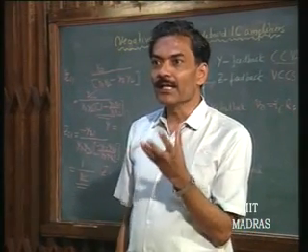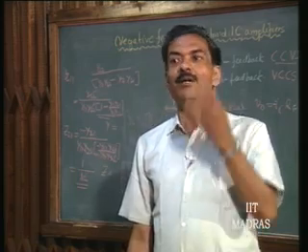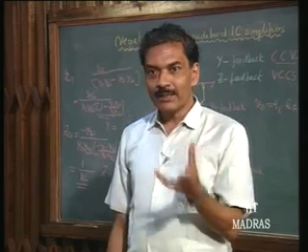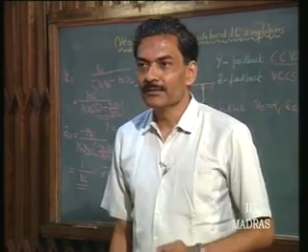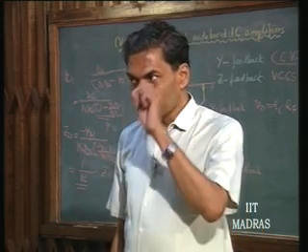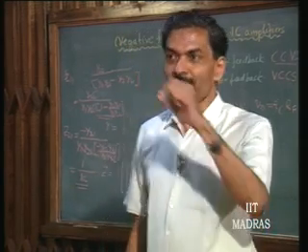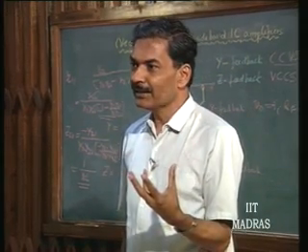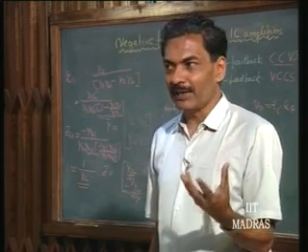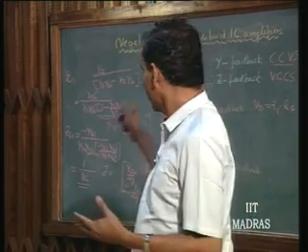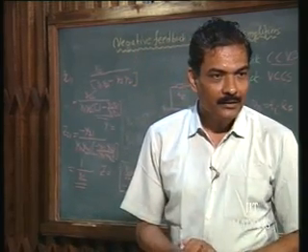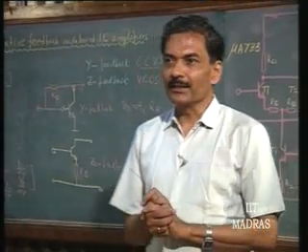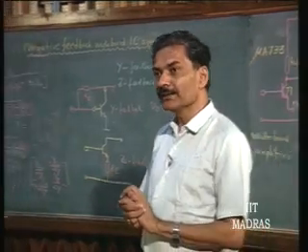y21 is still a large factor, assuming that you are using a good amplifier with a good forward transfer parameter, okay? In all the other factors, this forward transfer parameter will be the one responsible for making it go towards 0. In order to understand more clearly, you have to work out a specific problem and see how these parameters will have the widebanding effect. What will have the widebanding effect? The forward transfer parameter will have the widebanding effect. In this particular case of our example, it is the Z parameter, Z21, which is going to have the widebanding effect. So, does it answer your question?